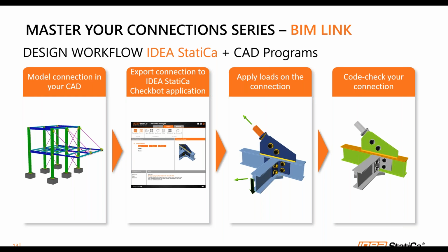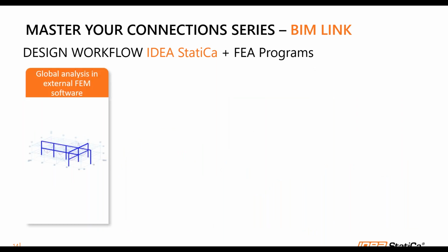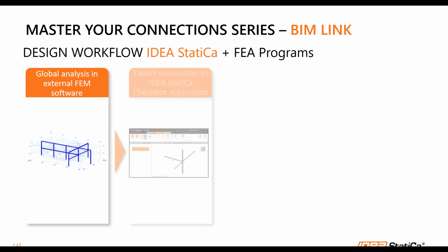And now the basic workflow for FEA programs. In this case, for example, you have ETABS, quite common here in Asia. You have SAP2000, STAAD.Pro, Midas. All you have to do is just export it to the Checkbot application. The difference here is that, the same as CAD, it captures all the geometry and the profile sections. In this case, the loads are now being captured, and the load combinations are now being captured.